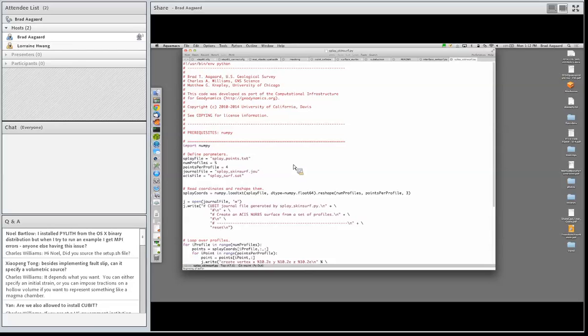So we're going to give it a series of, I believe, vertical profiles that then get formed into a surface. So you don't have to have the interconnecting curves. You can just give it a suite of contours and they'll sweep them together into a surface. It's called skinning the surface in terms of how Cubit refers to it, Cubit and Trellis.